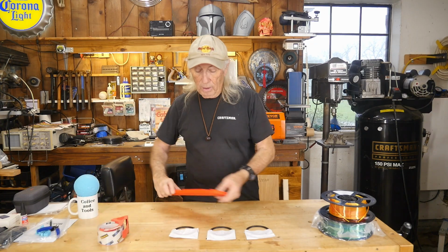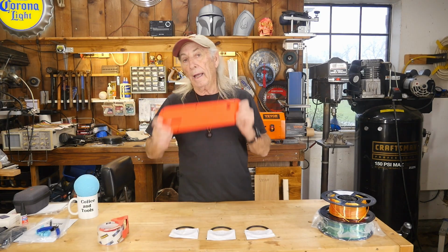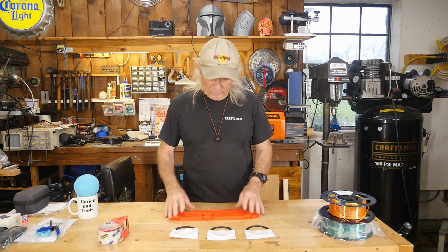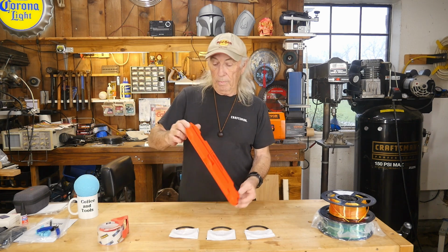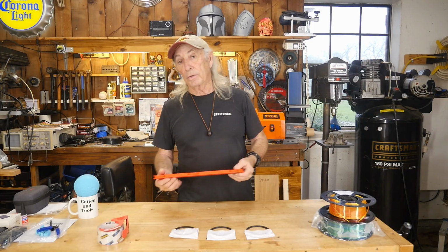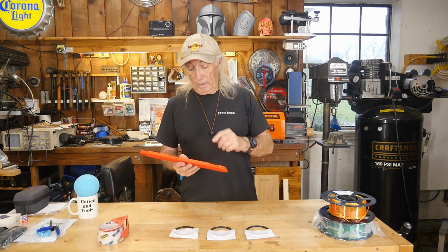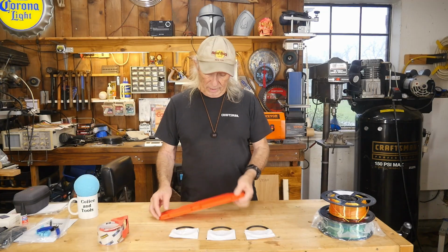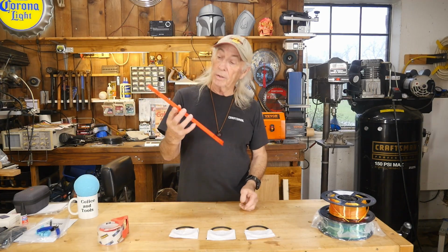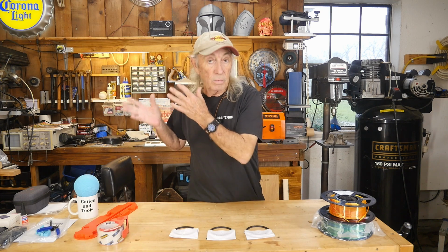There also was a problem with orbiting the model. That's where we take a model, we have X, maybe Y, and you might have Z. Well, what happened with Plasticity was I was unable to turn the model this way to orbit, and just have a look at the angle and say, okay, this is where I need to get through. It wasn't doing it. Now, that could be a number of reasons, but with 25.8.1, I can hit the shift bar, use the center mouse button, and I can orbit the model into a different angle to take a look at something, and at the same time still go ahead and make my cut. And again, bravo, fabulous, because that is part of the problem.